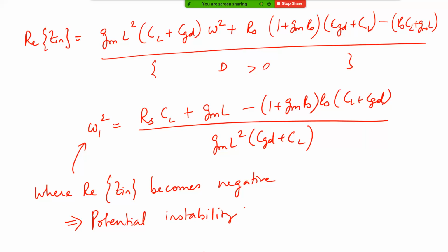In electronic circuits, instability basically means that the amplifier starts to oscillate. Now that you have negative resistance at the input, because of some stray inductance and capacitance, since once you do layout there will be some parasitic components coming along, it can just start to oscillate at some frequency given by the effective L and C of the whole network. That is what we call potential instability.